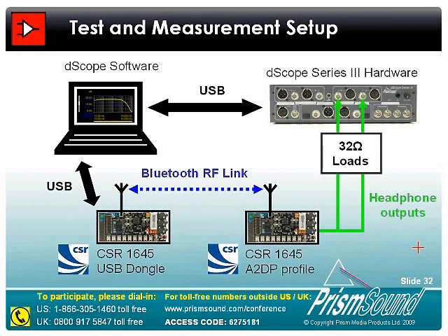And I'm taking the headphone outputs from this board, but I'm being careful here to use a purely resistive termination impedance at the output of my headphone amplifier, so that I can ensure that I'm driving current into a known load, and I can then use that known load to calculate the power delivered into the load. And 32 ohms is a standard load resistance that we often use for making headphone measurements, because they are typically designed to operate with that kind of a load.